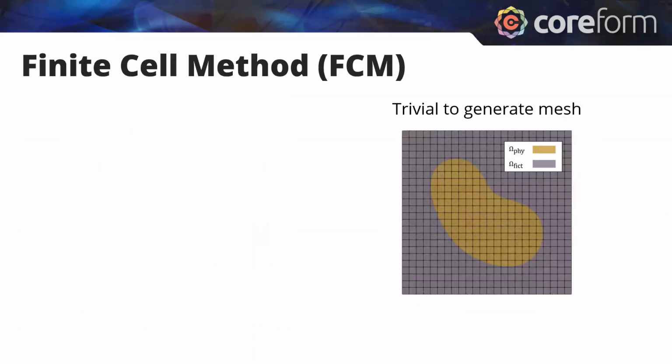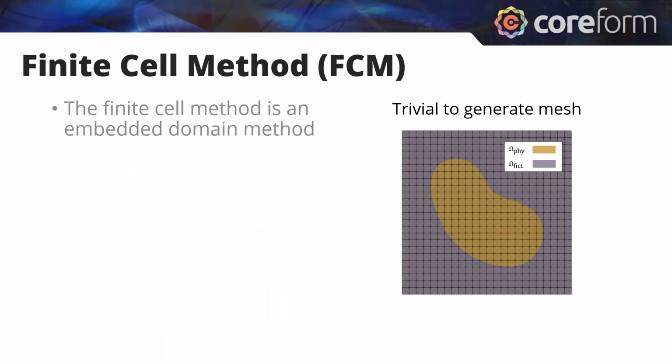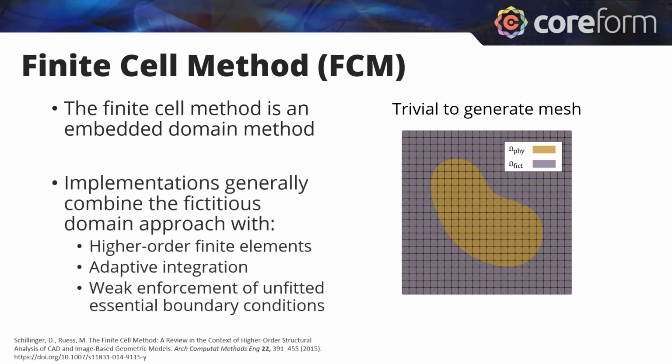So there's a method that you may have heard of called the finite cell method, which is really starting to respond to that issue. You take a geometry and you immerse it in what we call an envelope domain. And that now is a trivial to mesh volume. It's this embedded domain method, you hear them called immersed.